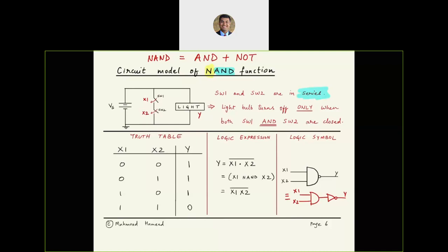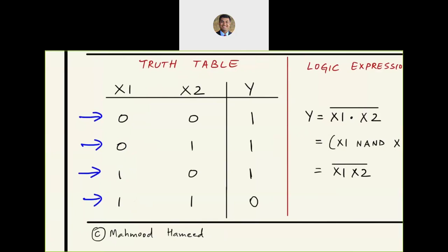In a general case, if you had m binary inputs, how many different rows would you have in this truth table? Well, you would have 2 raised to m, where m is the number of inputs. You would have m because of the number of inputs, and you would have 2 because we are operating on binary inputs. Binary inputs can have 2 levels. Now, the next question, which is very useful, is there a particular pattern that I can use to fill the input side of my truth table? For the output side, I need to know the logic function, but for the input side, there should be a pattern, and there is. The rightmost column of the input simply alternates 0, 1, 0, 1, 0, 1, and so on.